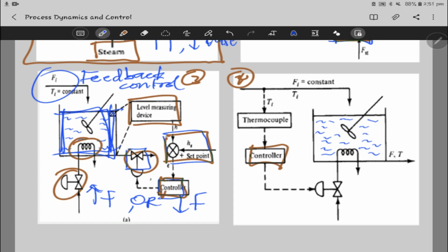But what we have in example, figure 4, is what we call a feed-forward control. You see all this here, we know clearly that these ones are the input. We are not measuring anything concerning the output here. We are still concentrating on the input. Basically, we've described the system already using an equation, and we know that if the temperature or the flow rate exceeds a particular limit, it will deviate from how we want it to be.